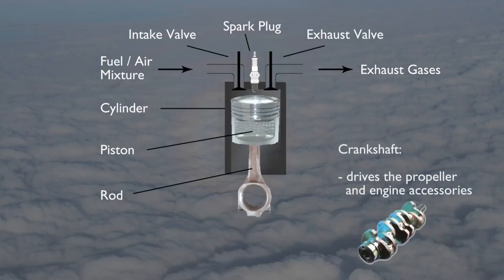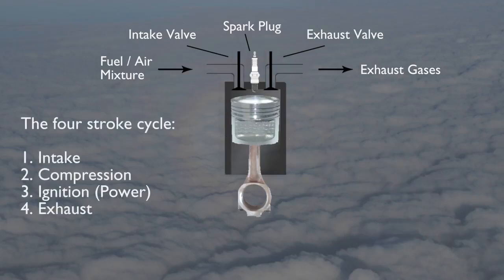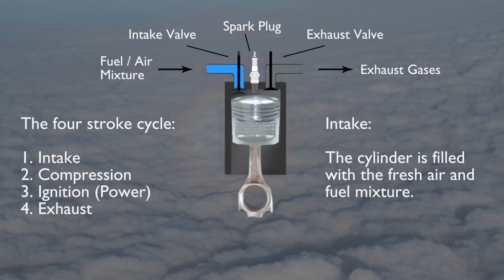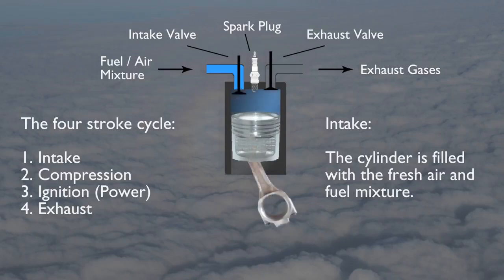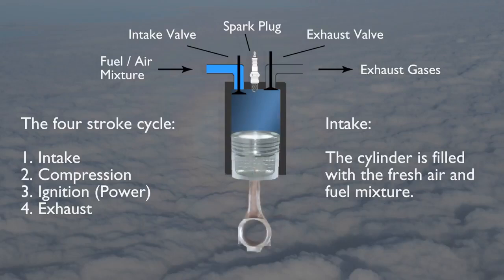The engine operates on a 4-stroke cycle. The first is intake. An intake valve opens, allowing a highly flammable mixture of vaporized fuel and air to rush into the cylinder. When the cylinder is filled, the intake valve closes.